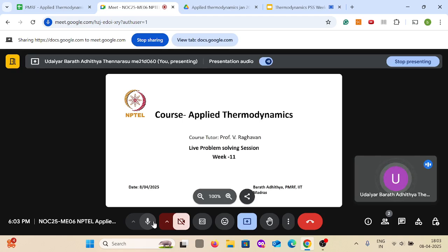And what is this Mach number? So Mach number is your velocity of the flow divided by your speed of sound. So that is your Mach number. And when this Mach number is lower than 1, you call this subsonic flow. And when it is equal to 1, where your flow speed is equal to your speed of sound, in that case you call it a sonic velocity or sonic flow. And then if it is greater than 1, your speed is greater than the speed of sound, in that case it becomes supersonic. So you have subsonic, sonic and supersonic conditions defined based on your Mach number.